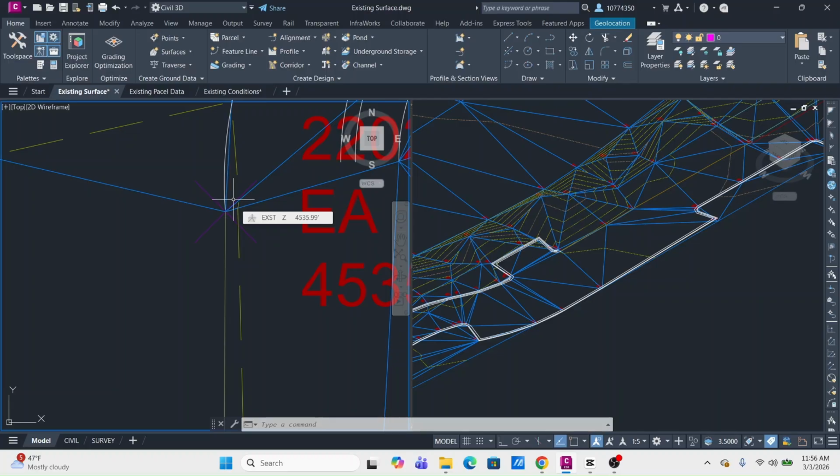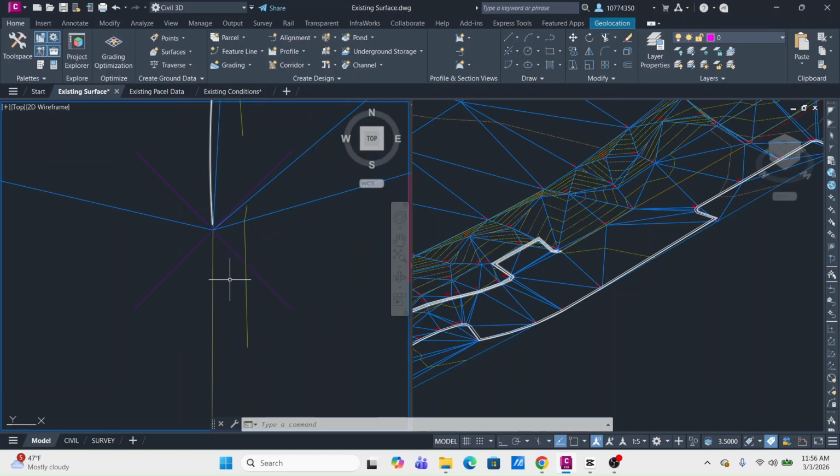It's just a weird thing. I don't know if AutoCAD's ever fixed this, but that's just something I've noticed. If they're just ever so slightly not touching each other, it should not create problems when creating break lines and triangles between the break lines. So yeah, just have that guy off just a little bit.